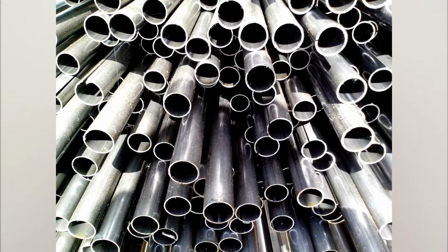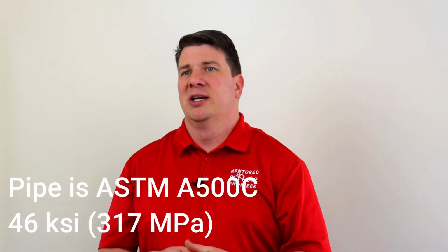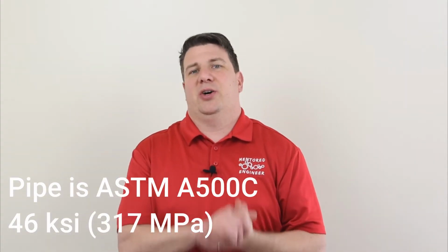Let's talk about pipes. Pipe is probably the least customizable one. You get your OD that you can customize, and you get your thickness. So pipe is very weak compared to the other steels, and it's generally only available in 32 to 35 KSI. So if you've ever been to a hardware store, you notice that 3/4 inch pipe doesn't have a 3/4 inch dimension on it, unless of course you cut it to 3/4 of an inch. The reason for that, I'm actually not sure of.